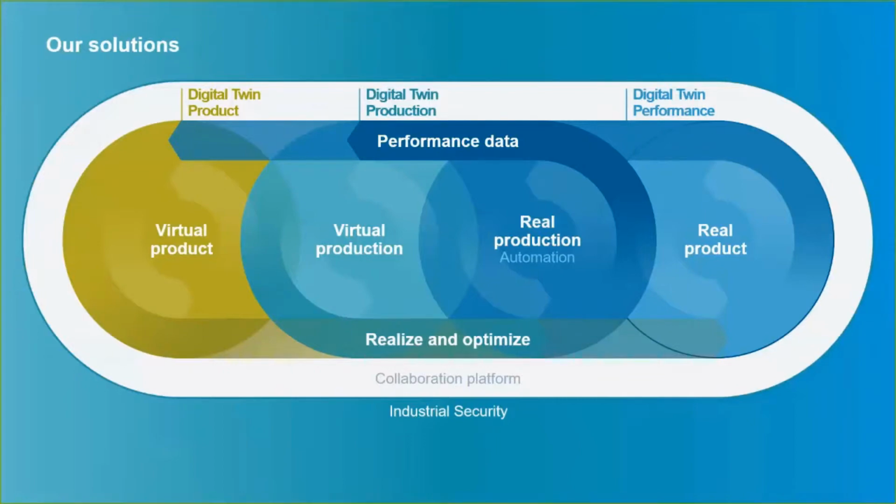And those tools look for simple geometry issues like excessively thin walls, excessive overhang, or completely enclosed voids where powder or supports might be trapped. Now, all of these solutions in their entirety complete the AM workflow from the virtual product through virtual production and into real production where the physical product is then produced.